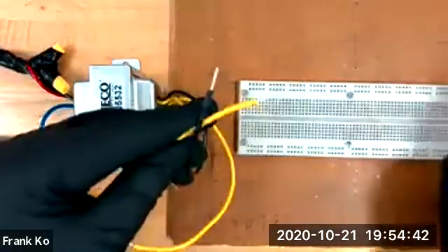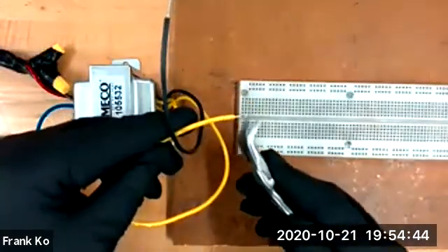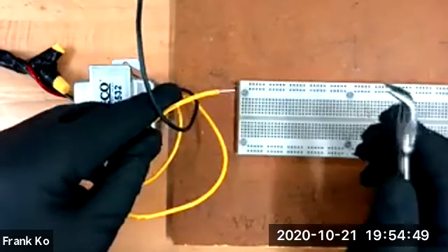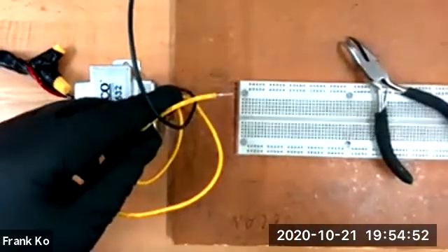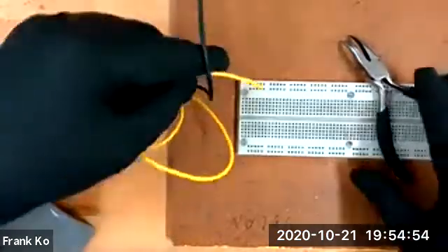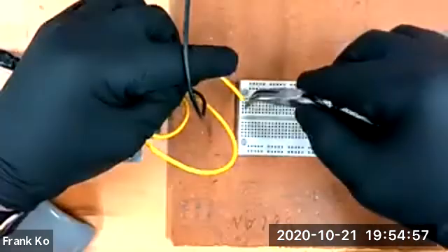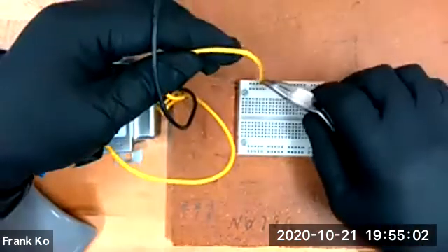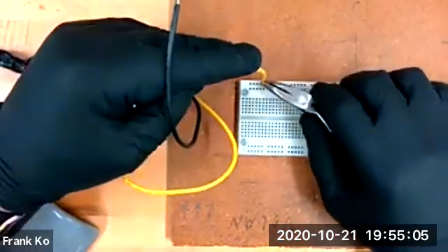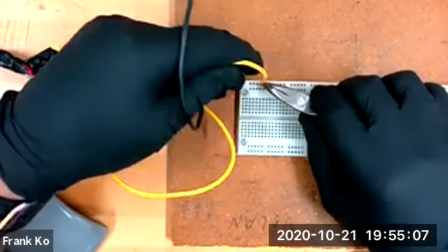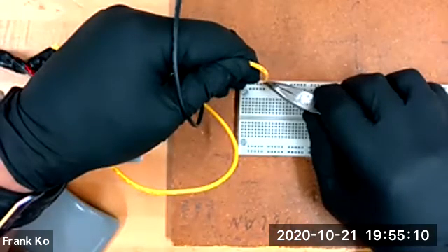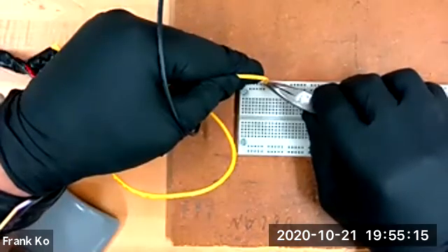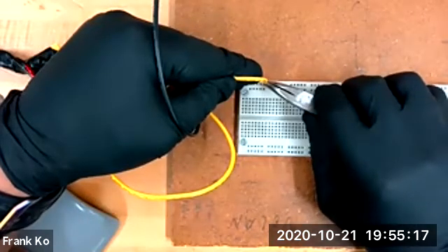Now these are already pre-tinned. My recommendation, so you don't bust the tinning on here, is to use needle nose pliers. You were supplied needle nose pliers for the specific purpose of giving you torque and being able to put the wires down. So you grab the wire like so, and then you very gently guide it into one of the bus rails. Find one that's cooperative and gently push it down.